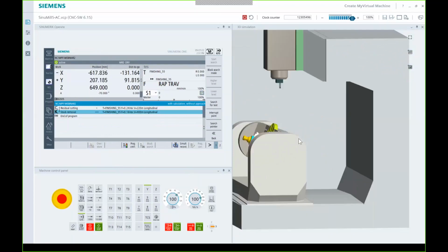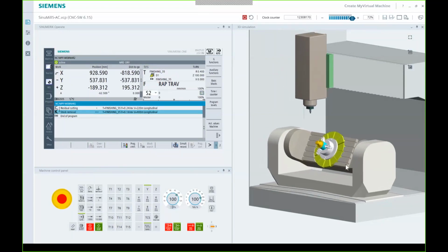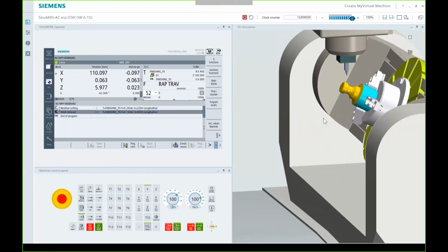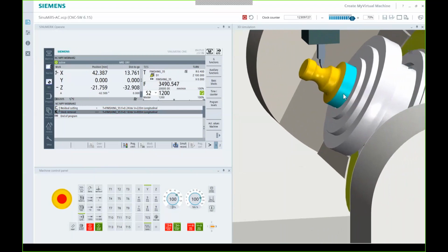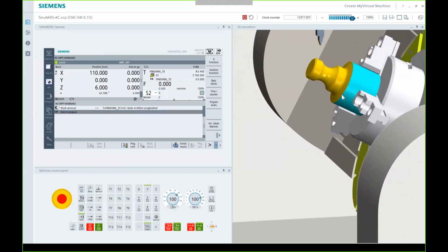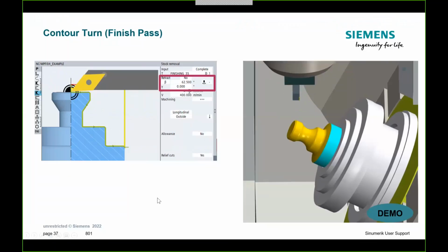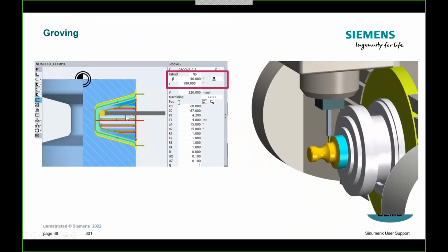So it's going to go up, do my tool change, request another cycle start to confirm I want to keep going, and we can re-engage, and now it's going to go ahead and do my finish bits. So now here's my finish bits. So this shape is now completely finished and ready to use, and all I have to do now is go back to my print, and now we need to add a groove to this.